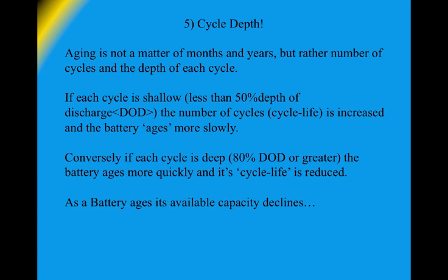In the full battery course, we'll see how I determine that and what it means to not go below 50% depth of discharge for extended periods of time, referred to as the autonomy period. Many of the battery designs we do allow for a 3 or 4 day period before we reach that 50% depth of discharge.